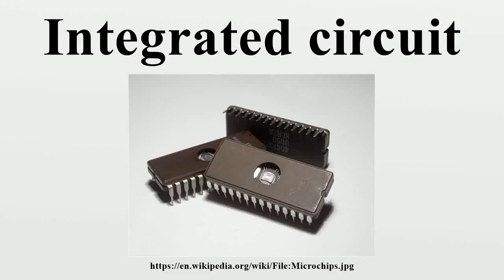An integrated circuit, or monolithic integrated circuit, is a set of electronic circuits on one small plate of semiconductor material, normally silicon. This can be made much smaller than a discrete circuit made from independent electronic components. ICs can be made very compact, having up to several billion transistors and other electronic components in an area the size of a fingernail. The width of each conducting line in a circuit can be made smaller and smaller as the technology advances. In 2008 it dropped below 100 nanometers, and has now been reduced to tens of nanometers.